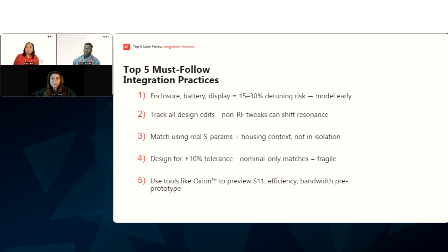All right. So I just wanted to bring up a few gems from my preparatory chats with Sifiso, and I wanted to open this as a discussion. We don't need the slides or charts. So Sifiso, some of the things that I picked up: you said on the bare board you can lose 10% inherently at low band. You also said for multi-layer, return paths and split grounds matter, it could be worse.